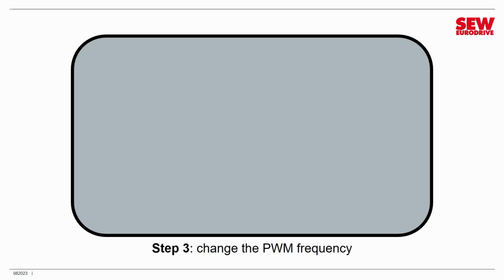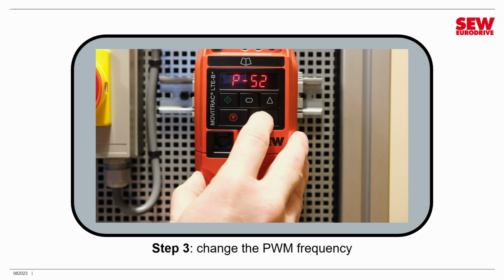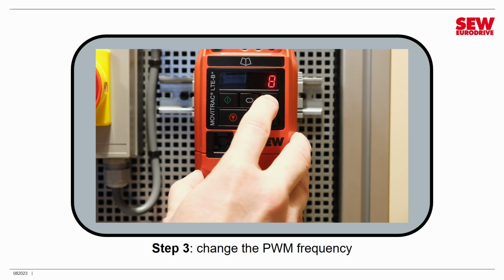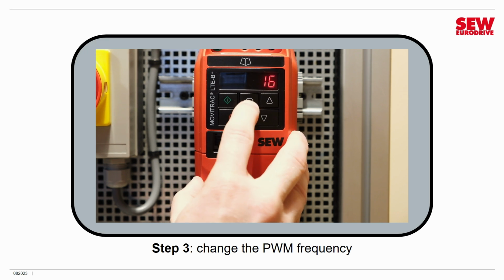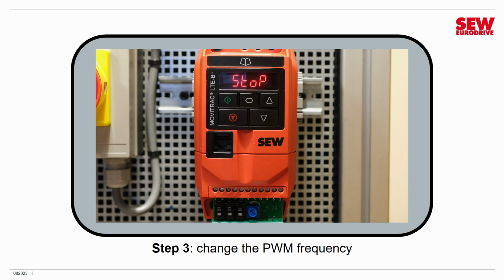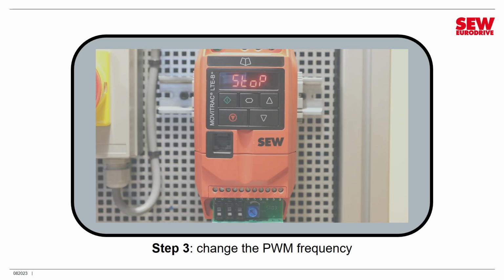So now we need to change the PWM frequency. So we go to parameter 17. And we change it from 4 kilohertz to 16, and I hit navigate. And those are all the changes I have to make. So I've done everything required. I hold navigate down for a few seconds to exit parameter edit mode.